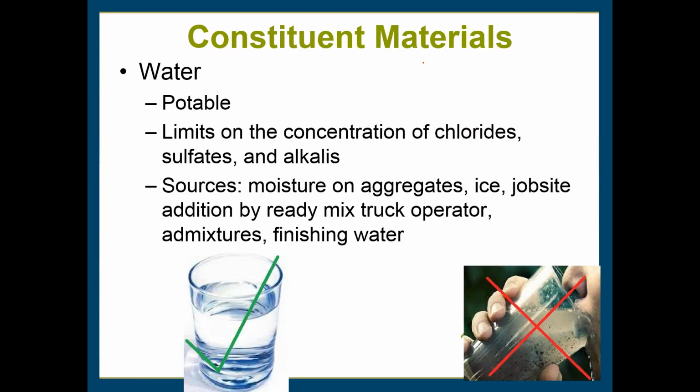Okay. Another cheaper ingredient that goes into our concrete is water. And again, this is another very important factor. So we require that you use either a municipal water supply, so we know that there aren't any little critters or impurities floating around in it. Otherwise, if you use well water, that's okay too. We just make sure that we get an annual potability test done to make sure that there aren't too many impurities or too many chlorides or too many of any bad things that would negatively affect any of the chemical reactions or the long-term strength of the hardened concrete.